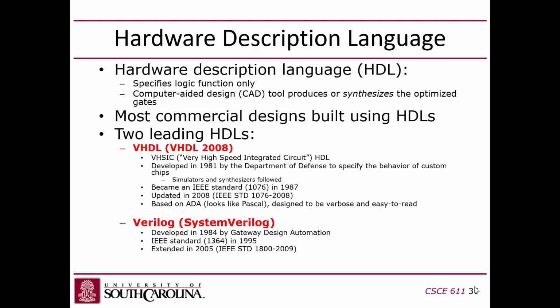The hardest part of HDL is not the syntax. The hardest part is the fact that HDL uses concurrent semantics, meaning that every line of code operates concurrently. There's no ordering to the lines, right? That's the biggest hurdle. Once you understand concurrent semantics, as opposed to sequential semantics, which is what you've learned up till now, then picking up new HDLs isn't too bad.